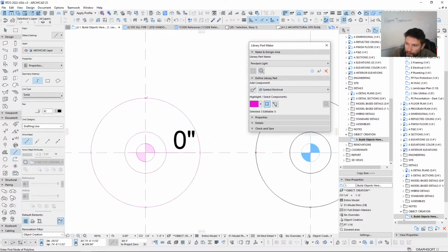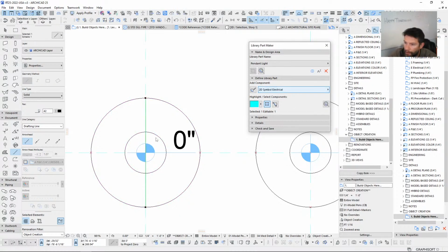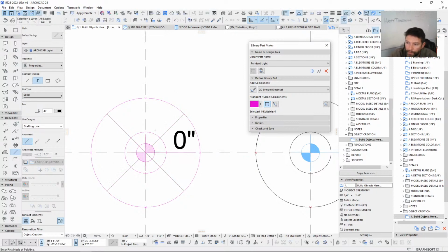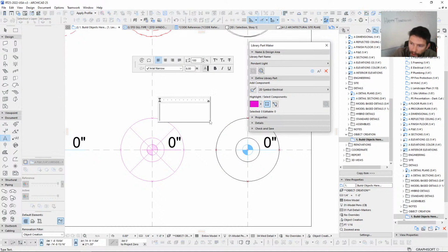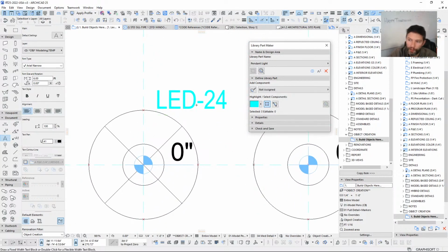And I think with our electrical, let's do something similar to what we did in our previous version, which was add kind of like a crosshairs here. Oop. Undo, Control E to rotate 45. We're going to do a Control Shift E to rotate. I think with this, we're going to call this an LED 24. So we can provide a light symbol here, but with this, we cannot assign text. That's one of the limitations of this workflow: you can't assign text into these objects.